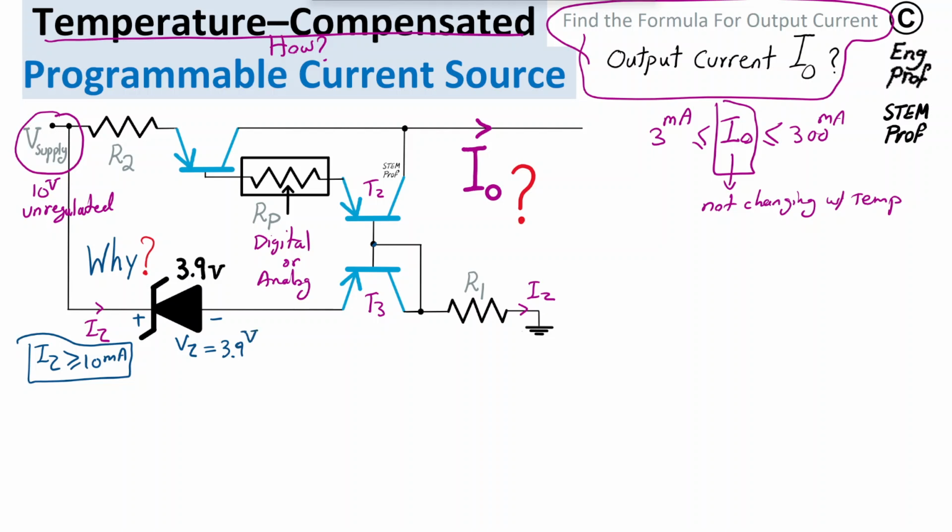But then as temperature changes from, let's say, room temperature, the value of this changes. By how much? By negative 0.06% per degree change in the junction temperature of the Zener diode. That's why we say the temperature coefficient for this Zener diode is negative 0.06% per degree change, or percent per Kelvin or per degree C. That's exactly what I used here.